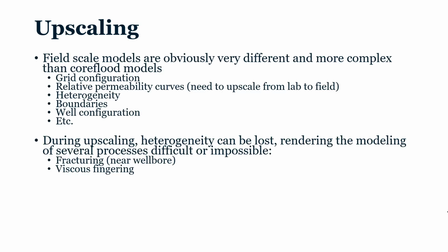We mentioned that. It's obviously way more complex in the reservoir. You need to take some inputs from the core, and the upscaling issue is an everlasting question, I would say. Imagine that you get a resistance factor in the core, at a given permeability. In theory, every cell which has the same permeability and same characteristics should see the same pressure drop profile, at least in terms of pressure drop.